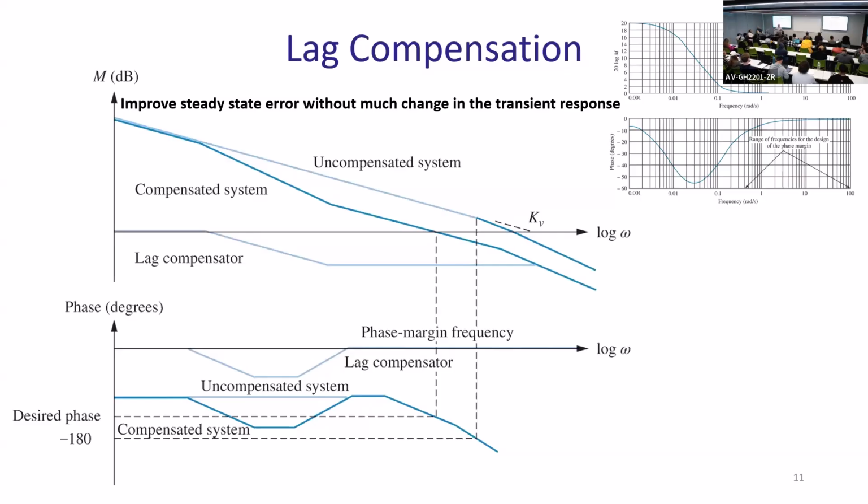Typically, you have all kinds of rules of thumb for how you choose different things for that controller, but we will discuss more or less the technical parts of it. And later I will discuss a little bit of how you play with the things. So pay attention that this thing is never zero. So you will add phase, actually subtract phase everywhere from your plot, the original Bode plot of your G system.